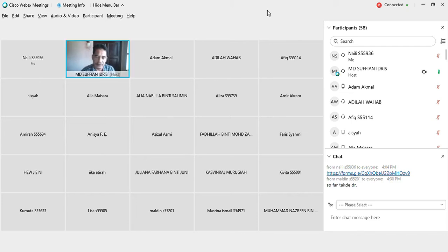So far, what you need to remember is the process. The first one is sensor calibration. You have to apply it to the image. The first step is to calibrate the sensor using the calibration parameters. And number 2 is atmospheric correction. It's very important to remove the effect of atmospheric noise. And then number 3 is positional registration, or geometric correction.